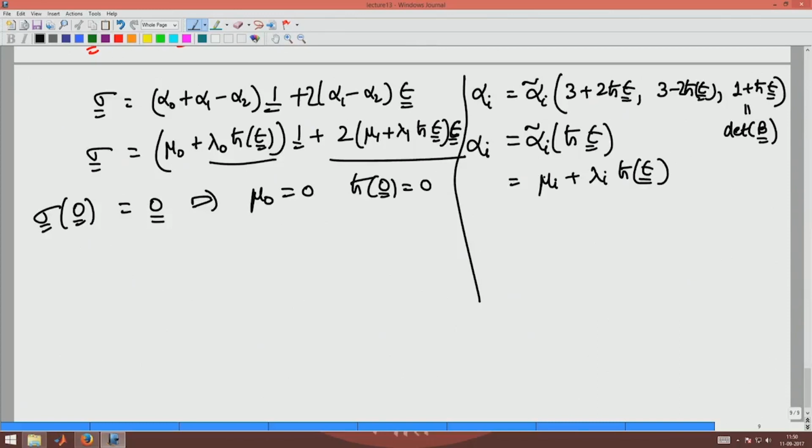Okay. Now, then I have here trace epsilon times epsilon, that is a nonlinear term, it will have gradient of H components which are squared, right, because trace of epsilon is epsilon xx plus epsilon yy plus epsilon zz, which is dou ux by dou x plus dou uy by dou y plus dou uz by dou z.